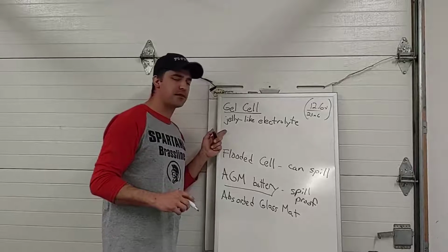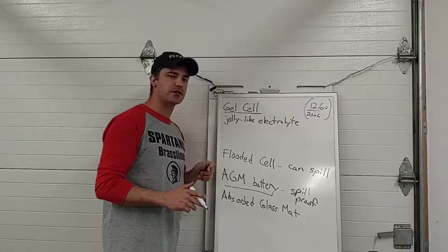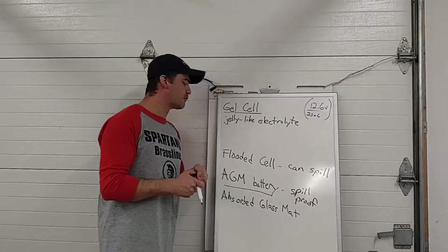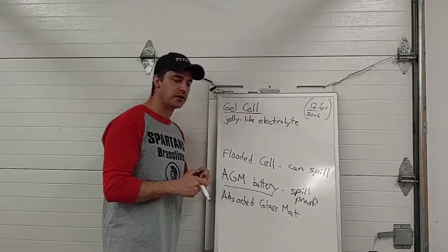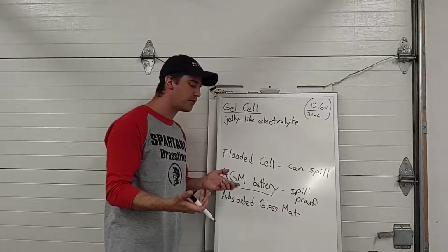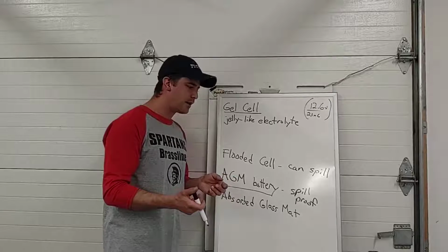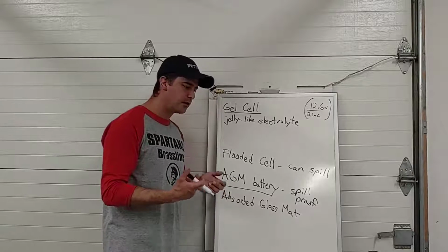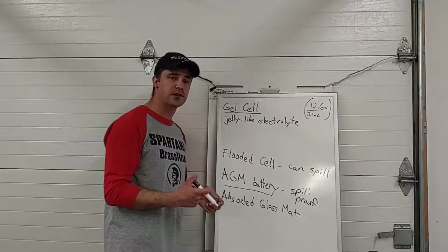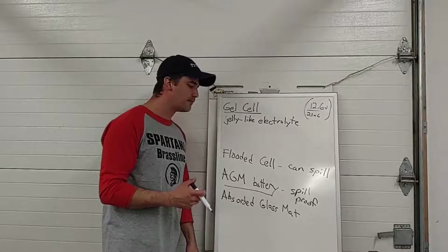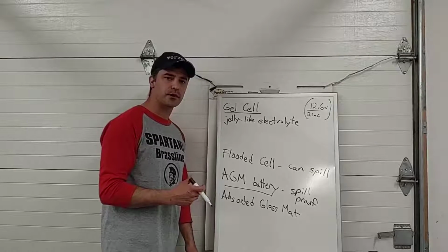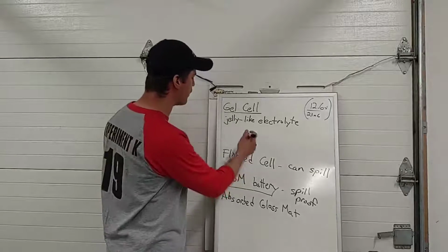They have a big drawback. They're very fussy about how they're discharged. They don't like really, really high current surges like your starter would be demanding of them, and they have to be charged kind of carefully. They need a very steady, continuous amount of charging current, and that's not really how the alternator and the charging system in an automobile works. So they're not really good for automotive use.